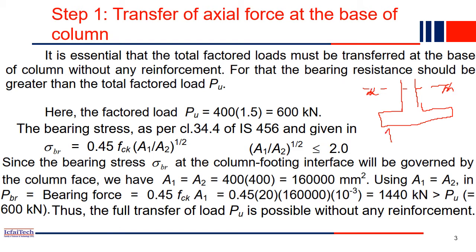So the soil will have some bearing pressure. This we call the bearing pressure of soil. If the quality of the soil, or the bearing pressure of the soil, is good, then the longitudinal reinforcement may not be required, or any reinforcement for transfer of load is not required.